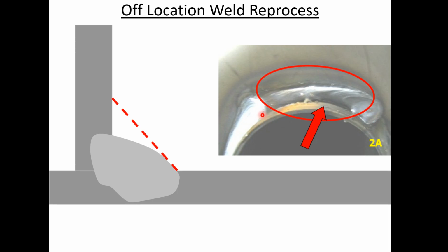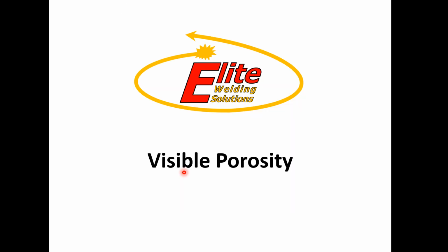So it's a very common thing that can happen with ever so slight fit-up issues, where the weld metal just has to kind of pick a side. It picks the side that has the most liquid and is drawn towards it. Simply by effecting a repair like this and putting it in place, you will have restored that leg length to where it's supposed to be.